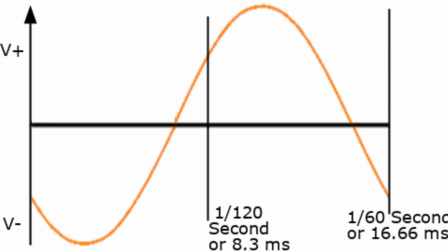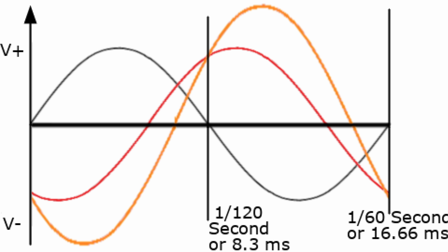So if we're only looking at the voltage from line to line, or from phase to phase, it would look like this sine wave here. Now you can see that this voltage here is greater than these voltages. It's greater than 120 volts. Again, we're sticking with the 120 volt system for now, although this all applies to other voltage systems. But this here is greater, but it's not double. You can see if it were double, this would be much higher. But anyways, this ends up being approximately 208 volts, assuming that this is 120 volts.